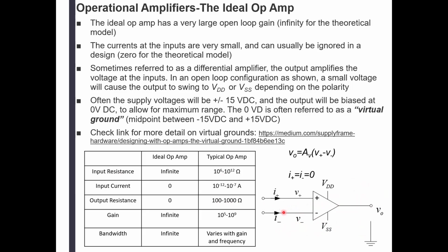So if we have, let's say, 2 volts here, and the gain determined by the combinations of the resistors and the connections here is going to be, let's say, 2. And the power supply is, let's say, 10 volts, for example. So if we have 2 volts times 2 because of the gain, we're going to have a calculated 4 volts. Is 4 volts as much as the power supply?